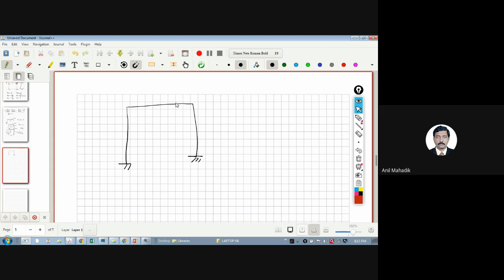If you don't tell Staad to do anything to this part, then it will by default be a rigid joint, or fixed joint. Staad Pro will automatically analyze this and give the bending moment like this, by default.